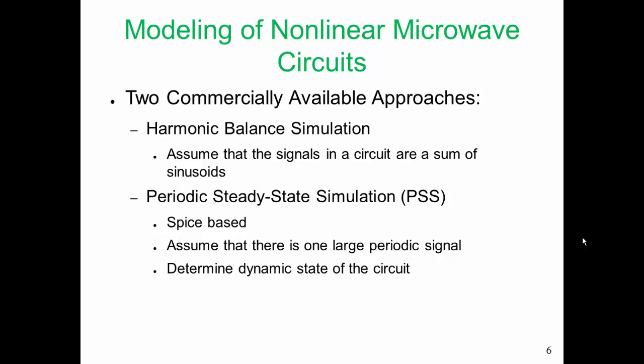When we're operating harmonic balance, we decide to separate or partition our linear elements into one block and our nonlinear elements into another. Since we are dealing with a fixed number of sinusoids at fixed frequency, we can characterize the external characteristics of the linear circuit using their S parameters or Y parameters. We do not need to solve every bit of the linear circuit over and over again.